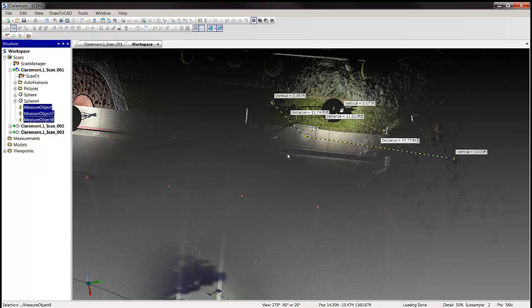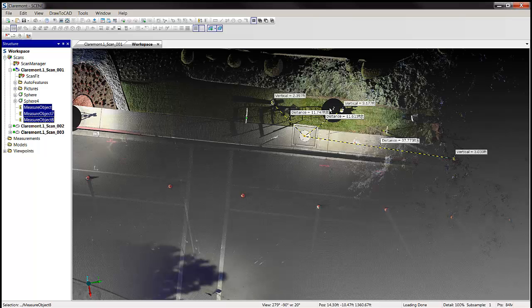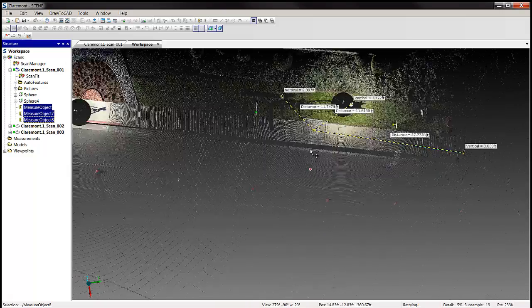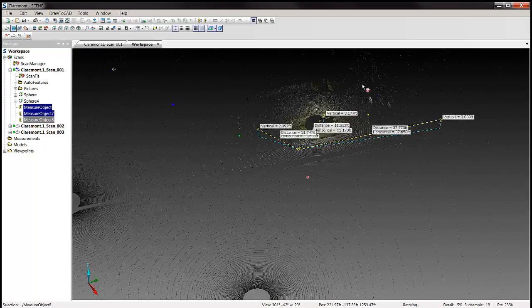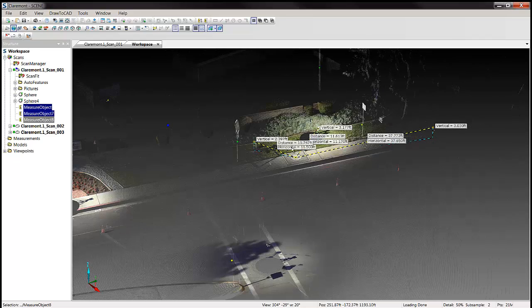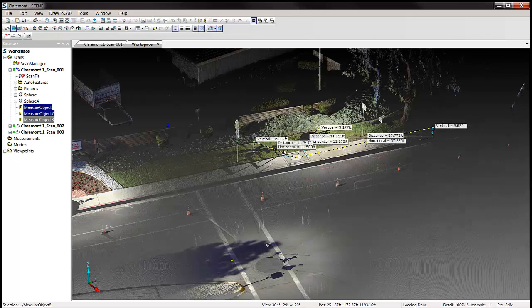So what I've done here is I've taken some measurements from the two vents, this vent here, and also there is a fire hydrant there. And I took 3 measurements so that I could triangulate the location of the center of that manhole. If you look closely, as I rotate this, you can see the horizontal measurements: from here, 11.5 feet, from this one, 11.17, and from the hydrant is 37.65 feet.